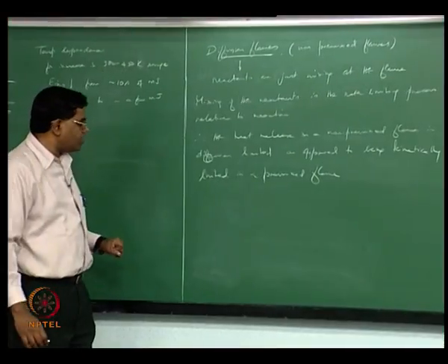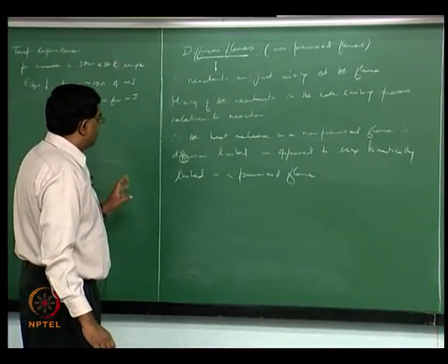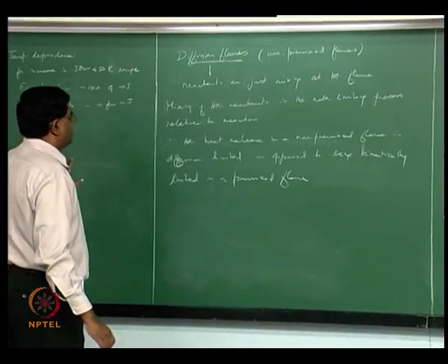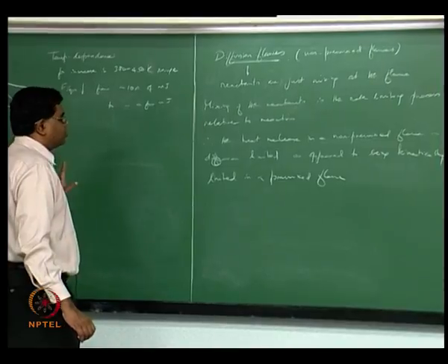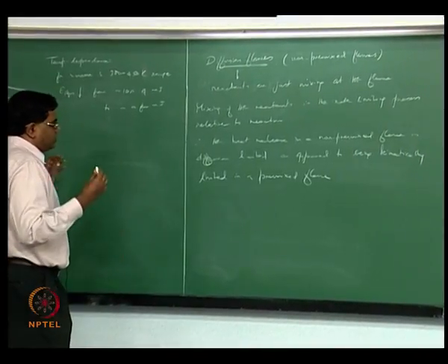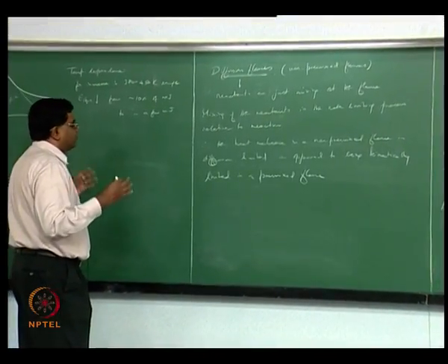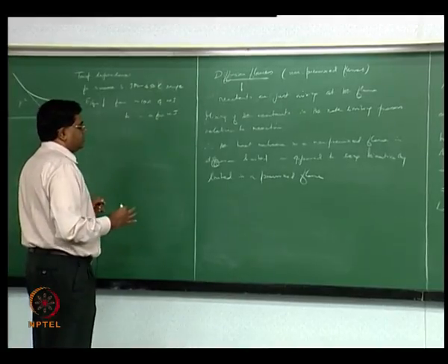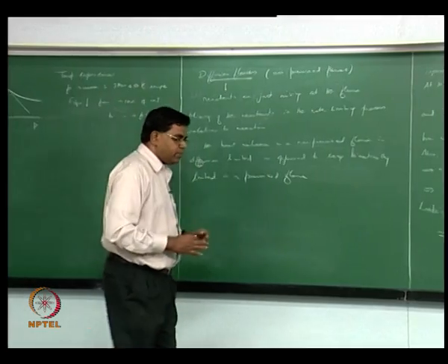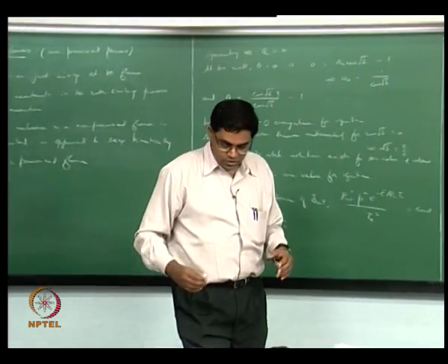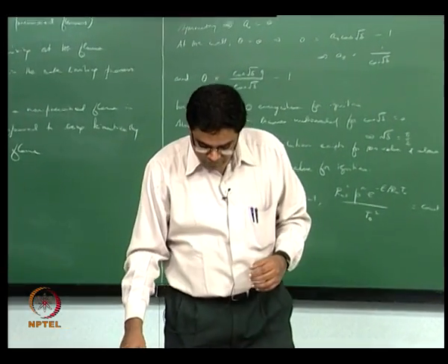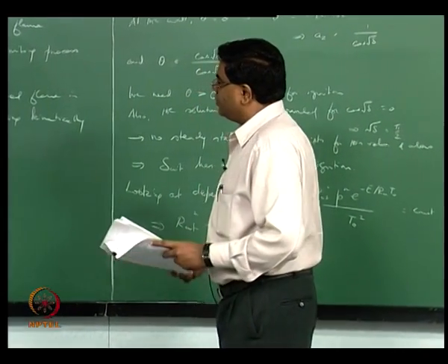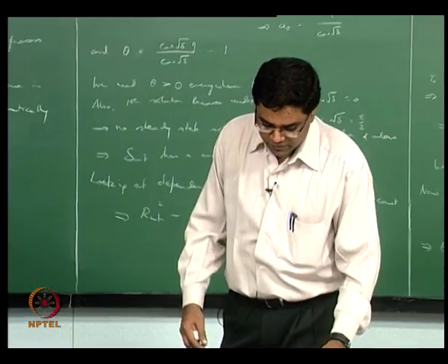Okay, so at the moment the idea basically is that diffusion is the rate limiting process, and therefore the heat release is diffusion limited, or the heat can be released only to the extent to which the reactants can mix, rather than whether they can actually release by chemical kinetics, like what is the chemical reaction rate based on law of mass action and so on. So the thing that we have to think about is,